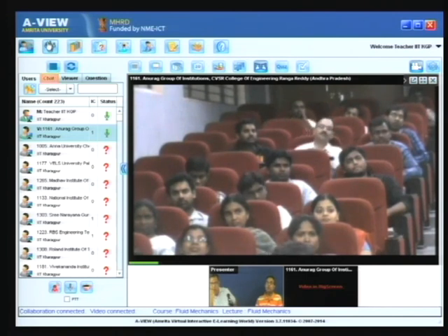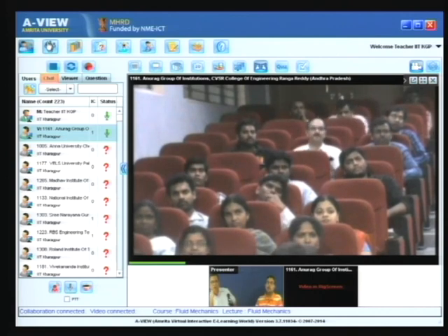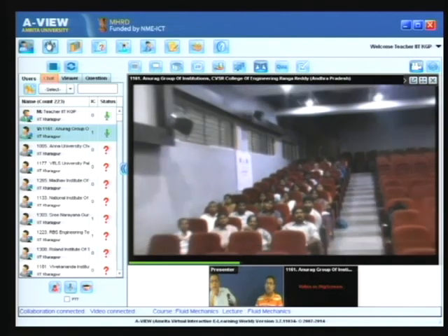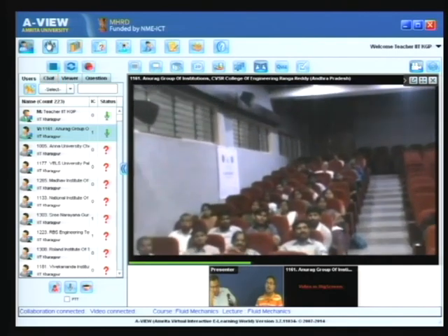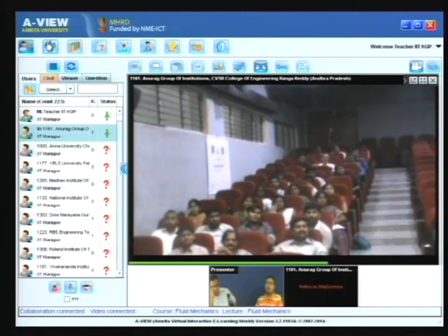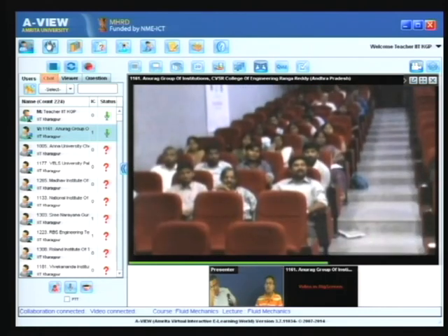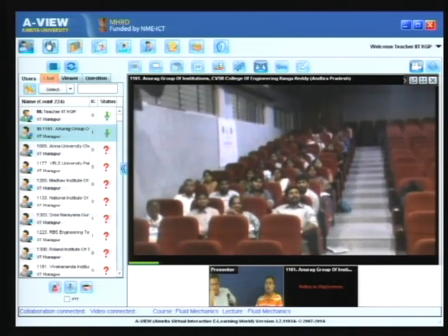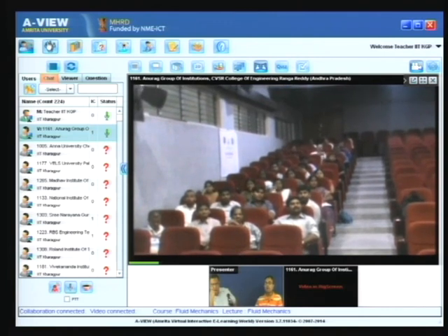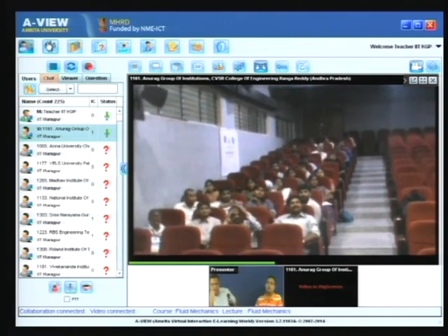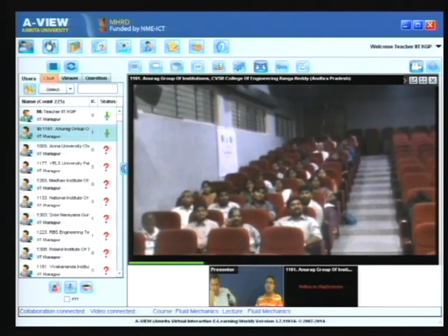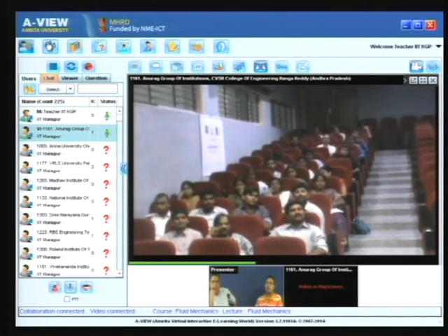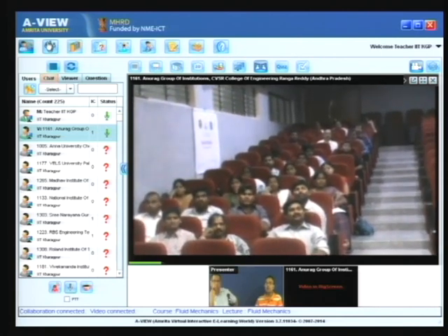explained by referring to the concept of a control mass system, where you have some identified mass. Now in fluid mechanics we are comfortable in writing equations of motion with respect to control volume. Not just equations of momentum, even the equation of conservation of energy we want to write in terms of control volume. So there must be a transformational law that transforms the mathematical equations for a control mass system to a control volume system, and Reynolds transport theorem precisely does that.